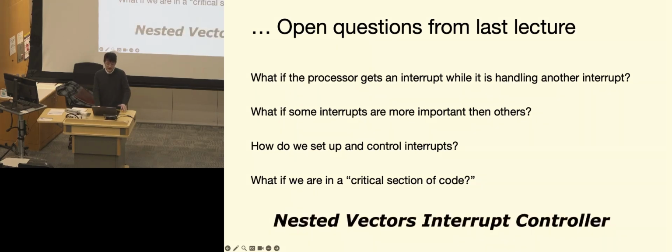As you would probably guess from the title of the lecture, this is mostly handled by the NVIC, or nested vector interrupt controller. It's a hardware module in the ARM Cortex processors that manages interrupt handling, priority levels, and nested interrupts, as in multiple interrupts happening at the same time. It enables efficient, low-latency interrupt control while supporting a lot of flexible priority schemes. That's very useful for you as a programmer to determine what should happen at what time and in what order.